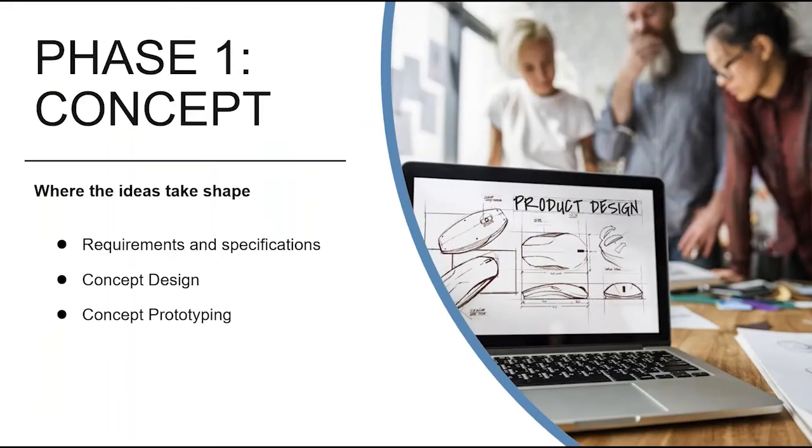So first step, concept. This is the beginning of the development of a new product. This is where we generate new and crazy concepts. Very important step because you define the requirements and specifications of the future product. So a designer or engineer would create a mock-up or drawing. Typically, they will make iterations until the styling lines and requirements satisfy the development team. At this stage, they mostly validate the look and feel of the product.